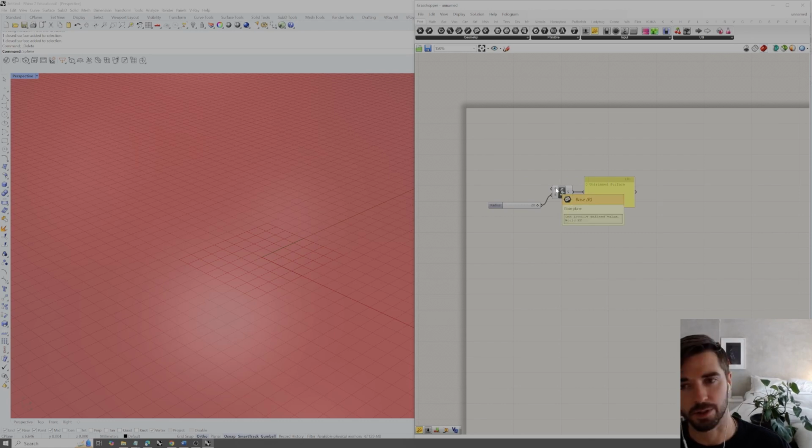Additional input for this component is going to be a base plane. So a base plane can either be defined with a plane parameter, or in this case, really what it's looking for is just that center point. Like when we typed in sphere in the command line, and all it wanted to know was a center point and then the radius, this also is looking for a center point, but it's just calling it a base plane. Really, it's looking for the origin of that base plane.